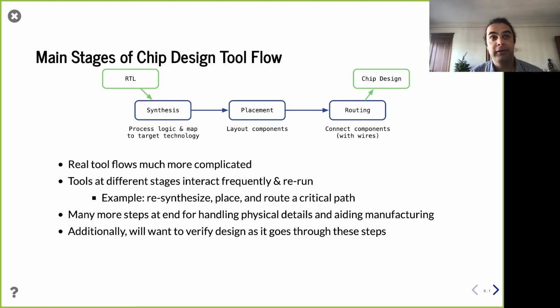Like I said, there are a lot of concerns in these modern chip technologies about how to make certain things map well to lithography and such, or just to get high yield, right? If your chip, when you make them, most of the time they don't work, and some of the time they do work, if you can improve your yield, that matters. So DFM is really important. DFT is the more important one, kind of answering your question, which is design for test, right?